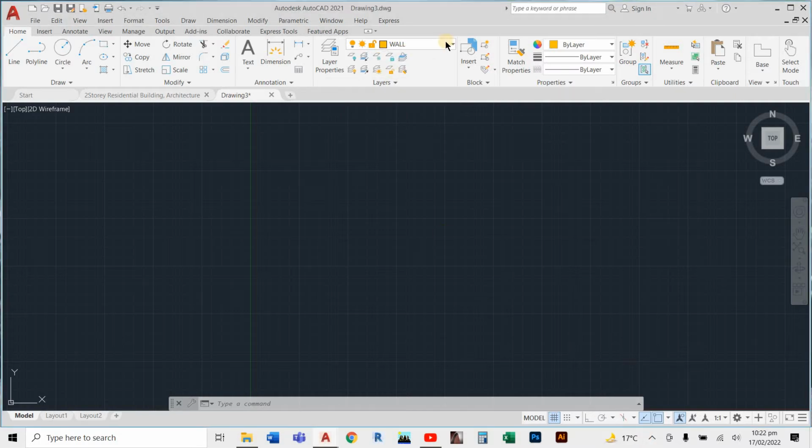So what should we do first at the start of the project? First of all, we should see the first episode of Start With Project. Second, we should open our AutoCAD, determine our units, determine our limits, and determine our layers. The layers that you created are all coming here, set current there. It's a default, don't think about this. So we start with the wall.